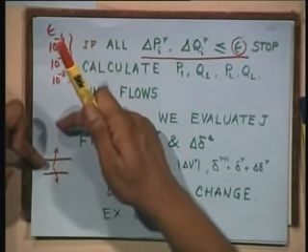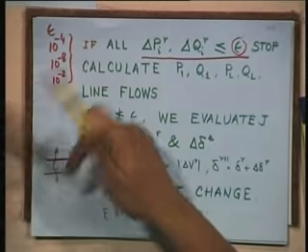So if it crosses an upper limit or a lower limit, the remedy is the same, you convert it into a change of bus type, PQ to PV or PV to PQ, depending on whether Q is crossed or V is crossed. If Q is crossed, PV becomes a PQ bus, you fix that Q and that becomes a PQ bus till you are back within the range, then you can change back. So this is a change of bus type.